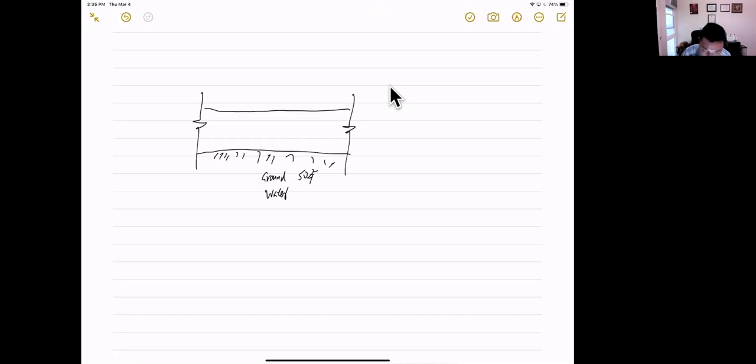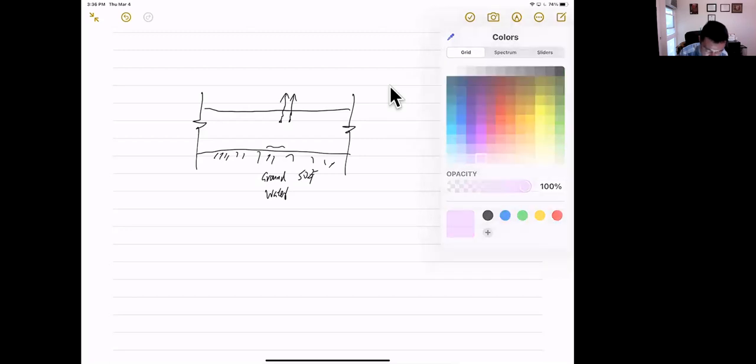When the concrete is porous, the water will evaporate. So the concrete on top, close to air, will be drier compared to the concrete here. That will form a gradient in moisture. So that's how the suction can lead to the continuous movement of groundwater through the concrete.